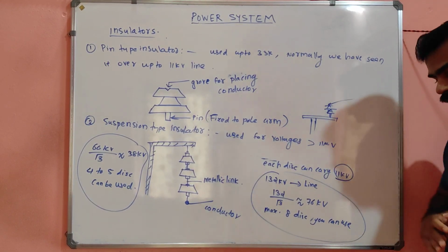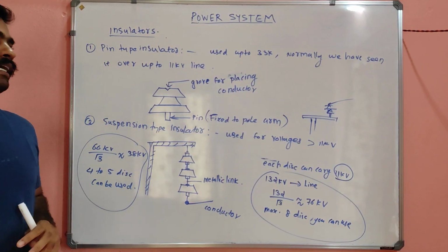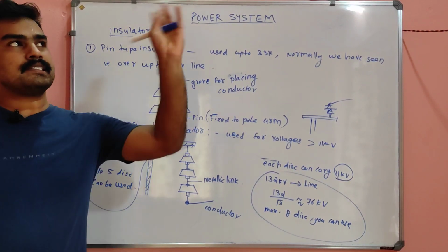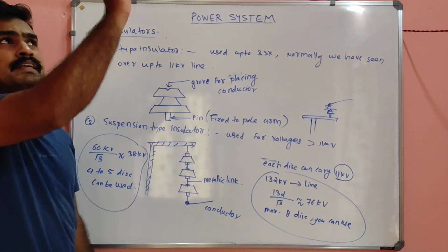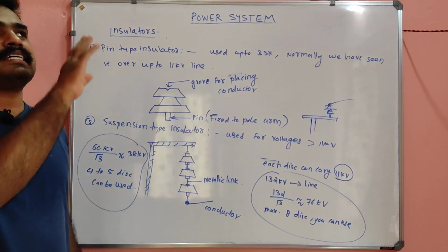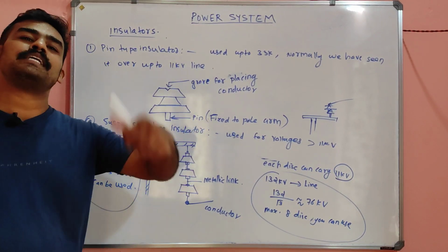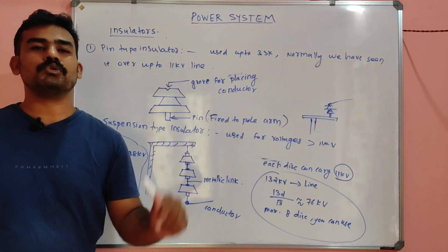And one more thing for problem solving, my dear, I will tell you a trick. In every question regarding a three-phase system, the given quantity is always the line quantity. So whenever there is a demand for a phase quantity, you have to convert it into the corresponding phase quantity and do the calculation. Okay.